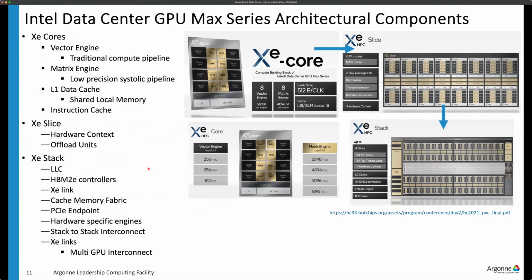Okay, so the core compute performance for Aurora comes from the GPUs, the 6 GPUs that are present in the blade itself, right? This slide talks about the GPU architecture. It builds upon how the processor itself is put together. The fundamental compute of the GPU comes from Xe cores, which are composed of different vector and systolic units and a bit of cache. Those are all put together into a slice with connectivity between them. And then this is built up into a rack. Sorry, not a rack, a stack.